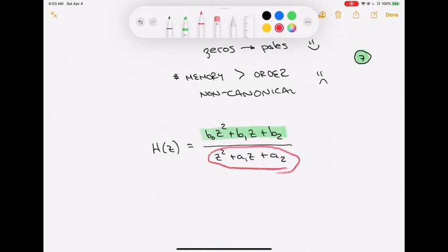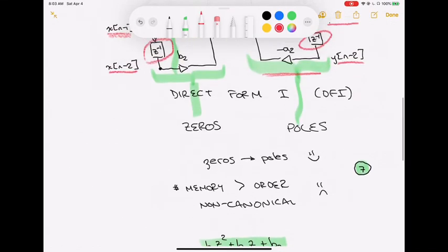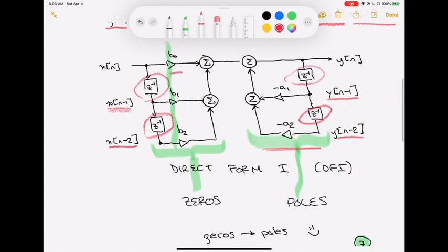So one of the nice things about this transfer function representation as well is that if you have the transfer function written, you can just draw these structures directly, because we just read off. We put this rational function in descending powers of z, and then we just read off the coefficients b0, b1, b2. And we go ahead and write that in b0, b1, b2, and we keep going. If it's bigger, just having a longer and longer delay chain.